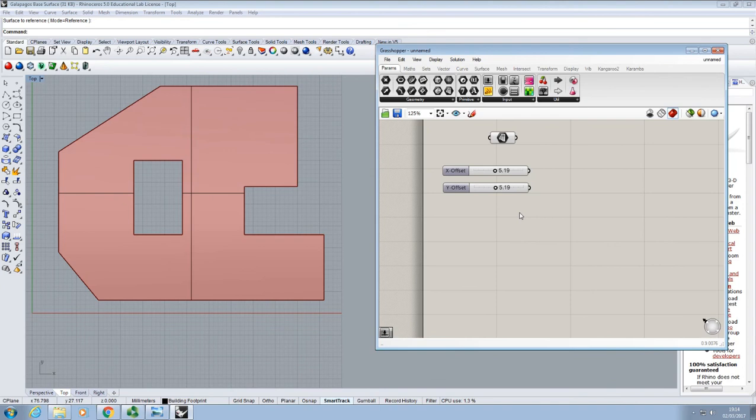And then the next thing we want to do is to have some sliders which will control our column spacing. So again, we're going to set up some sliders to do that. So using the lesser than sign is one way of setting up sliders quickly and easily. Another way of doing it is to type in the start number of your range. So in this case, I'm going to have these sliders going between a range of 9 meters and 12 meters. It's a reasonable sort of standard column spacing for steel frame buildings, at least.